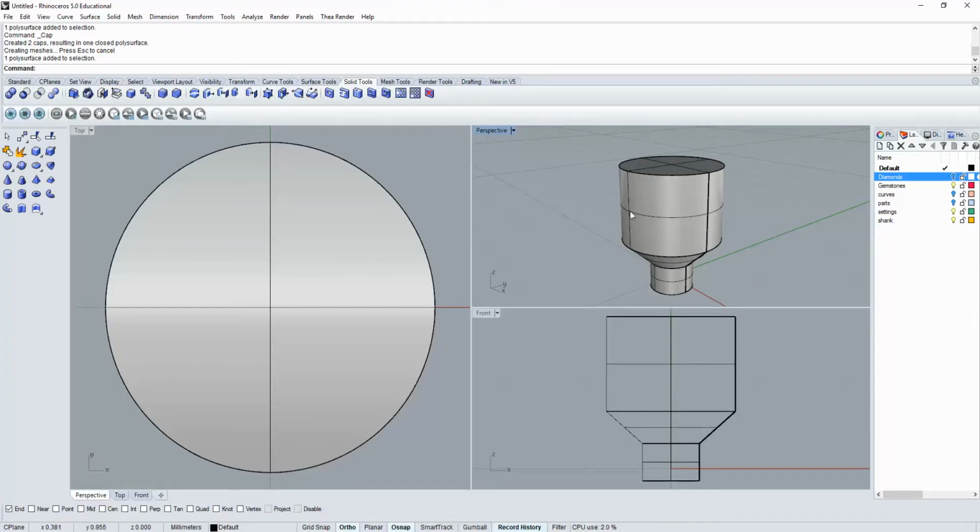I'm going to fillet the bottom of my cutter because I personally, in a lot of things, don't like the guide holes to go all the way through the piece. I think it can look really messy at the back. It depends if it's inside a dome of a pave ring, obviously, sure, put it all the way through. If it's a pendant, I might want a smooth back, or I might want a different detail on the back, so I don't want my cutters to go all the way through.